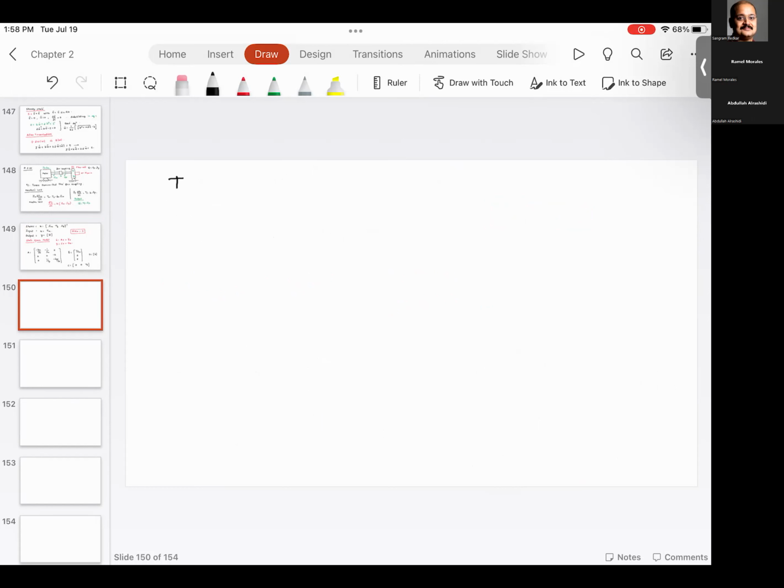It says Tm, which is the torque supplied by the motor, is given by this equation: A times S Vf squared divided by 1 plus S divided by Sb squared. Now S is nothing but the slip, so 1 minus capital omega m divided by omega s.